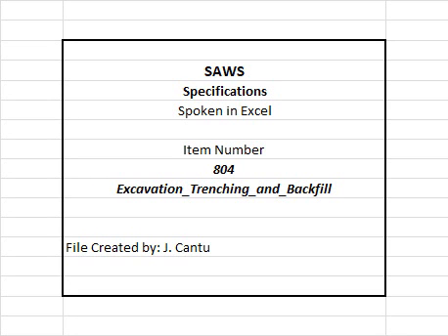804.1 Description. This section shall govern the excavation, trenching, and backfilling for water, sanitary sewer, and recycled water construction, unless otherwise noted in the contract documents. The work shall include all necessary drainage, dewatering, pumping, bailing, sheeting, shoring and incidental construction.